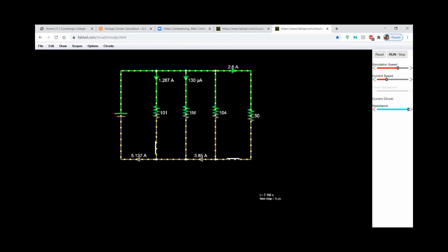you can see that I'm just simulating that that is an open switch. But what's happening to the yellow dots? You can see that they all pretty much stop, right? All these yellow dots that represent the current are showing that we don't have a flow. Through the ammeter, because I am using 1 mega ohm, it's telling me that I have 130 microamps. But in this case, it just means that we pretty much lost that load. If this was a resistive load for heating, we just lost that heater. You're not going to be getting any heat from 130 microamps.